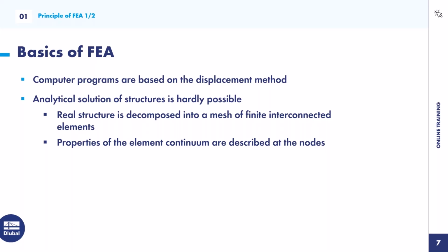And inside the element, we have approximations. There are different approximations and several programs can use different approximations. Also, there's the difference between linear approximations or third order approximations, which would be a more exact calculation, but also result in a more demanding computer power.